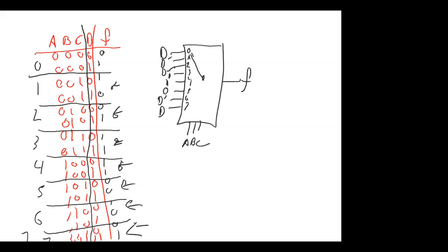So now what's cool about this 8-to-1 mux is it's just implemented a 4-variable truth table with no K-maps. Single chip, the 74157, right? Sometimes they write 157 because it's understood that the little apostrophe means 74157.